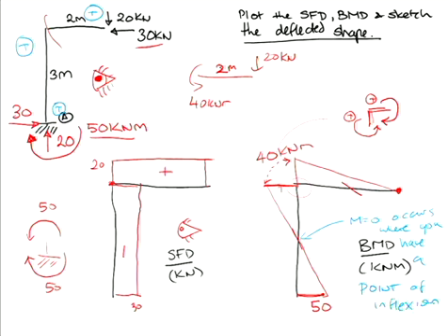So, how do you think this thing is deflecting? We know at a fixed support there's no initial rotation, so we have to draw it effectively vertical. But to have tension on that side, it must be moving to the left. And now I'm going to, this is exaggerating, now I'm going to draw a point of inflection. About there. And my corner here is what I call an inner. It stays at 90 degrees, but I've got tension on the top.